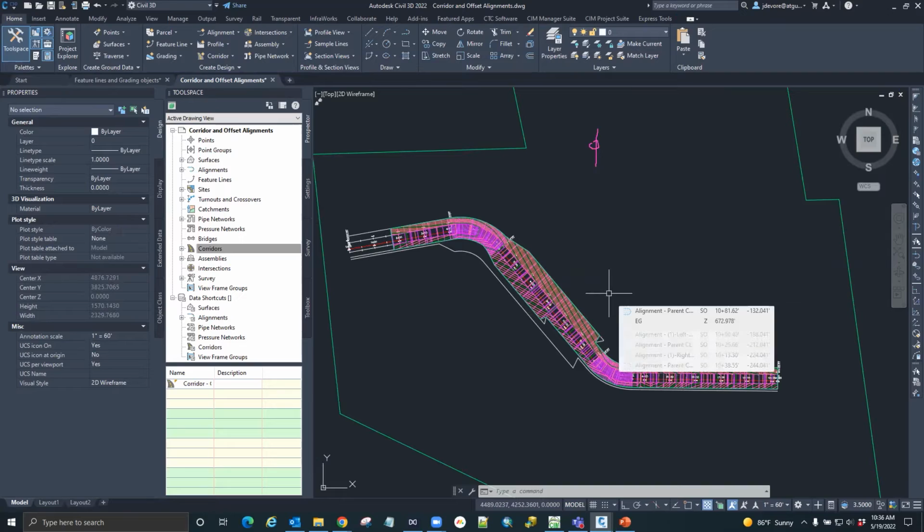You can have, let's say, your curb assembly on a commercial site, and you can have your feature line be your flow line, and then you can add this in. Now whenever you update this one feature line, your flow line, your corridor will create your top of curb and back of curb. If you have a sidewalk in here, it'll do your sidewalk. So like with residential projects, when you update one thing, you're updating multiple things on your surface, and it's all staying dynamic, which is ultimately what we want: as much of our project to be dynamic as possible.